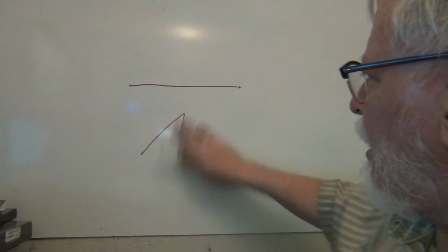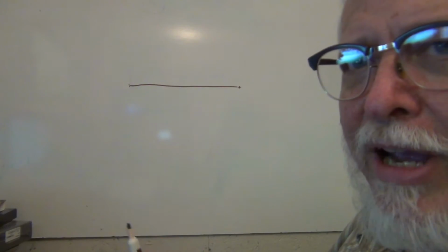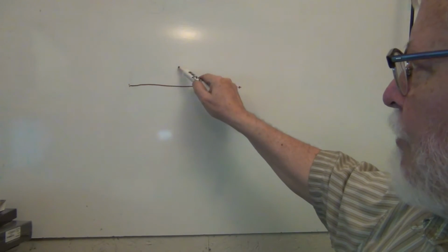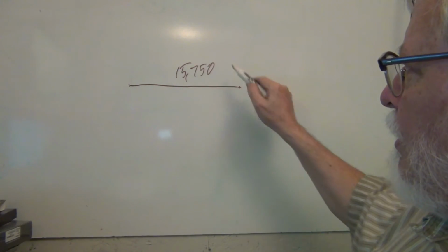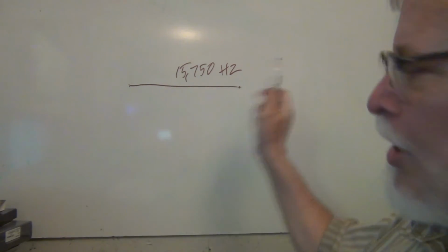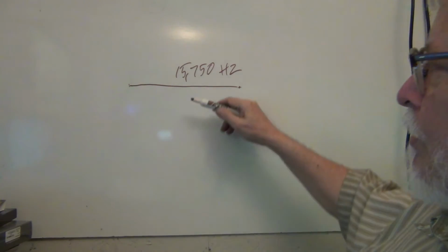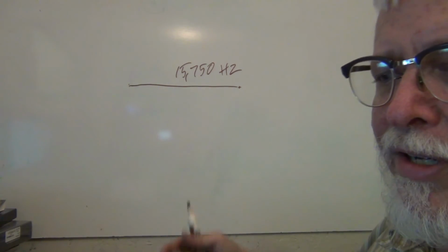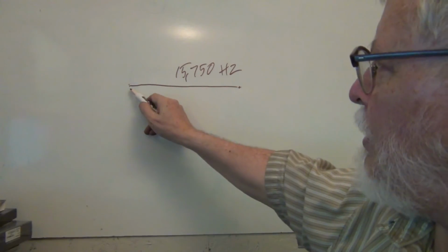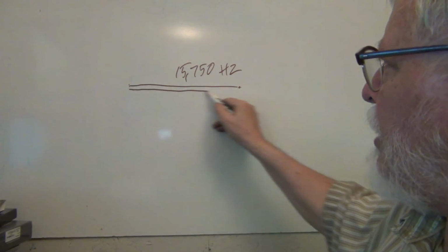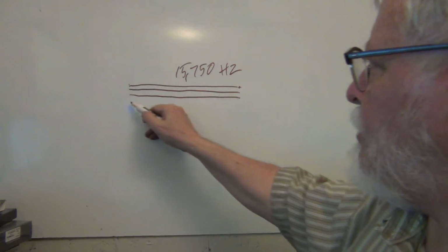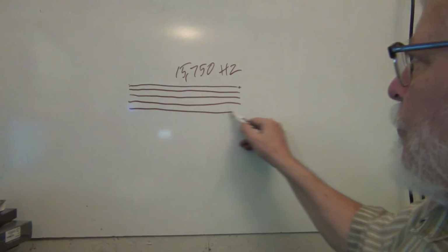But where it gets interesting is then if you make another ramp that's much, much slower. So like at regular TV rates, this runs at 15,750 hertz. 15,750 times a second, that sawtooth makes a line. Okay, well then if you take another sawtooth that's much slower that runs at 60 hertz, then what's going to happen is by the time it retraces and gets ready to draw the next line, it's moved down a little bit. And then the next line, it's moved down a little bit, and the next line down, and so forth.